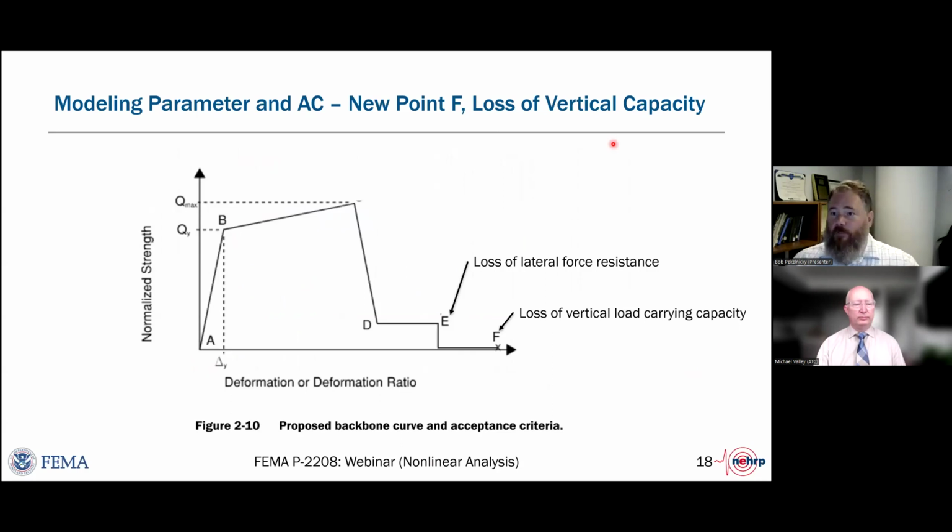So as I said, one of the things that you are held to as an unacceptable response is the valid range of modeling. And so what we say in the standard, and I apologize for not being clear on this, is that if you know what point F is, that is your valid range of modeling. All 11 records have to keep the response within point F. So while there could be some changes in the ground motion hazard, we're hoping that by using 11 records, you've properly captured the statistical distribution of the ground shaking. Okay, very good.